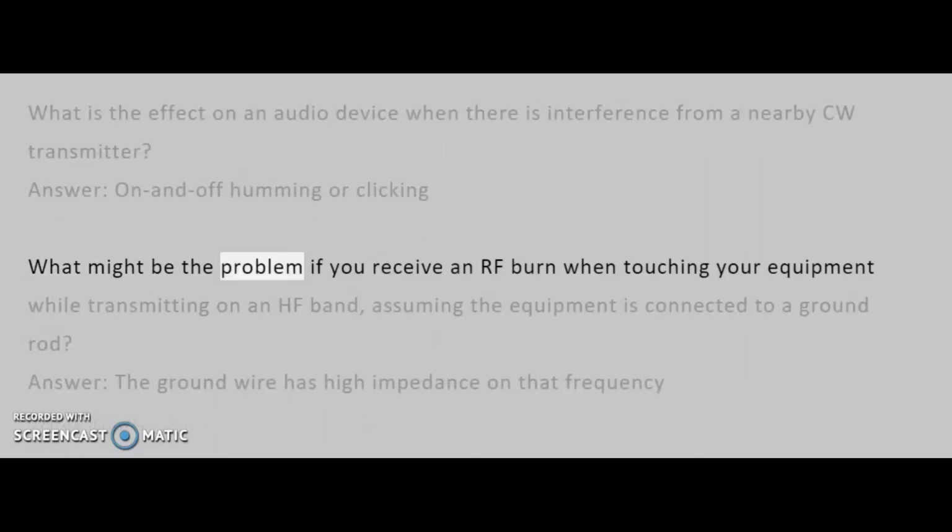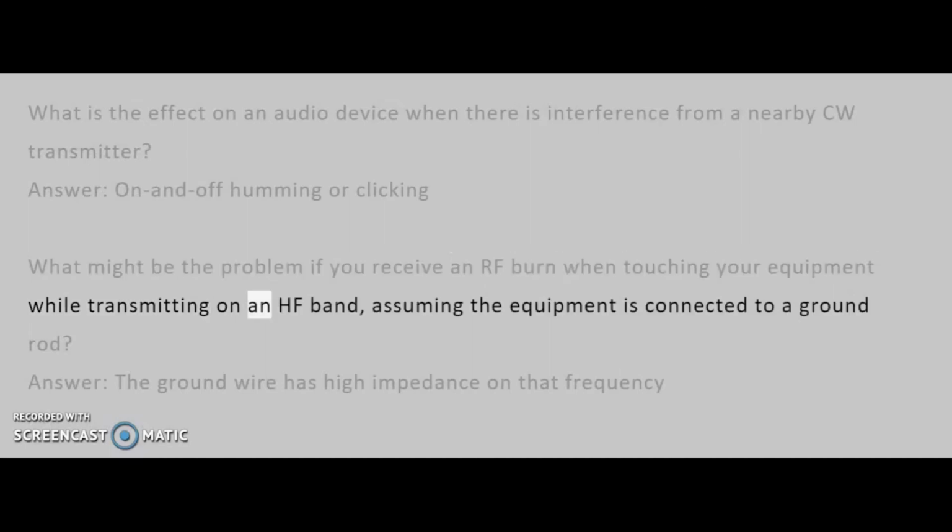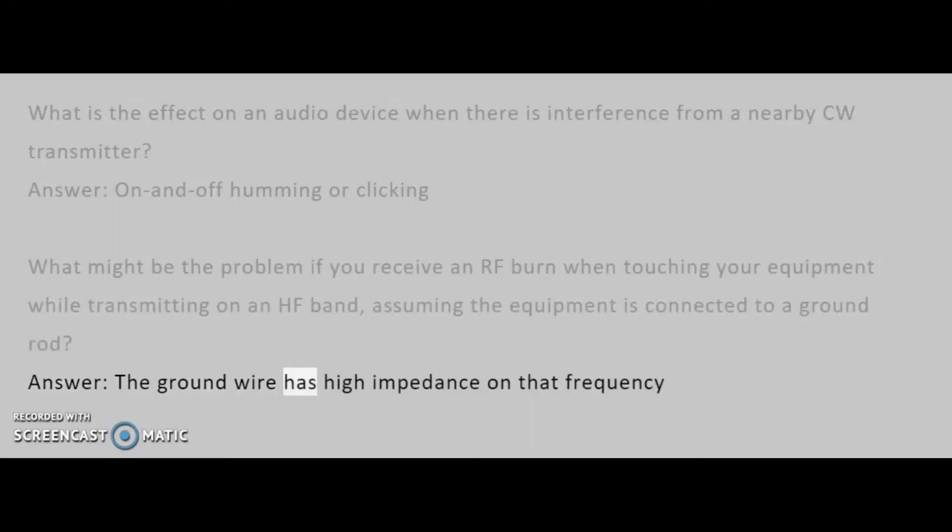What might be the problem if you receive an RF burn when touching your equipment while transmitting on an HF band, assuming the equipment is connected to a ground rod? Answer: the ground wire has high impedance on that frequency.